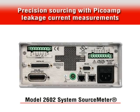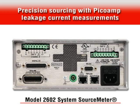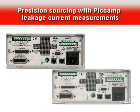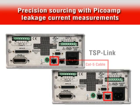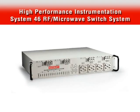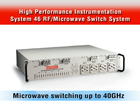Measure picoamp currents, and with the 2600 series system source meters, save space by combining 2 channels in one half-rack instrument. Save test time by using the 2600 series to execute control and measurement test scripts internally and reduce interface bus traffic. If your device has multiple RF inputs and outputs, add a System 46 microwave switch to the system